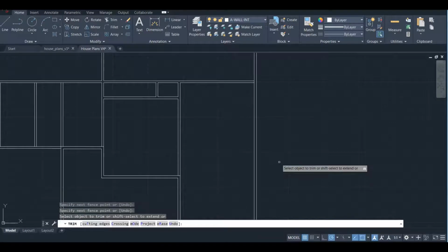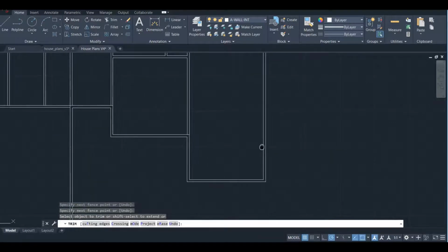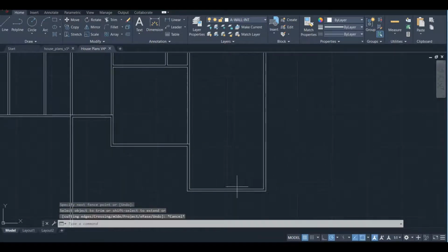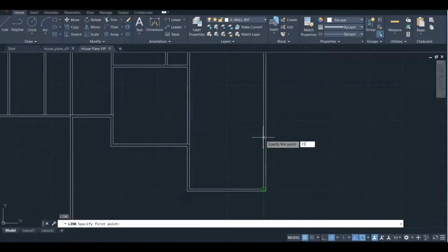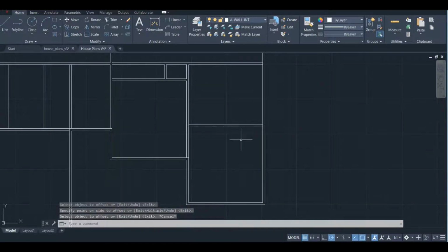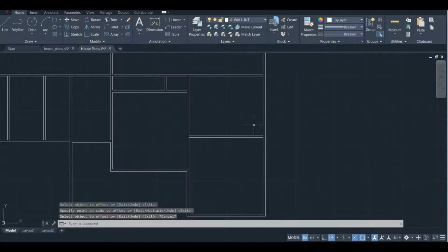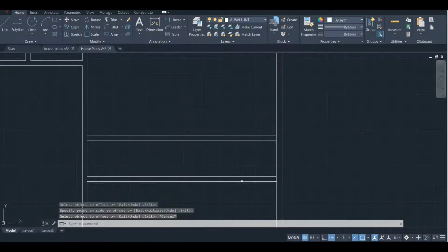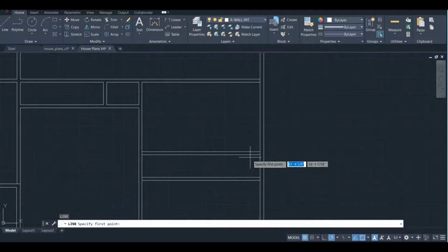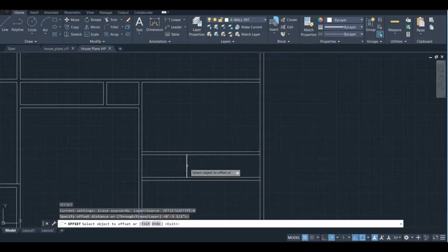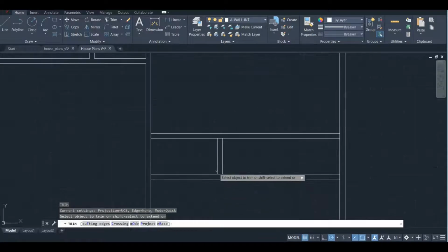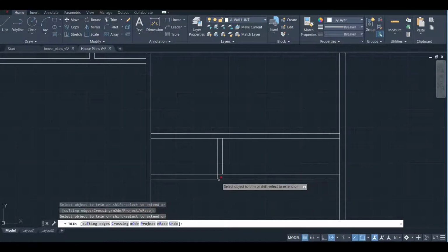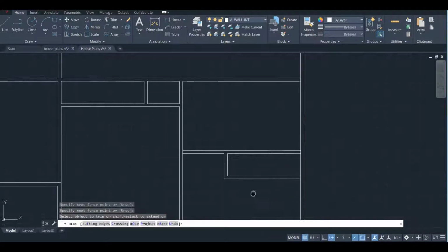This other bedroom is 11 foot 4 inches deep. So draw that wall in. So I go up the wall, and then it's got a closet right here that's 2 foot 1 inch deep. 2 foot 1 inch. The closet is 6 foot 10 inches wide. A cool thing about trim is you can actually hold shift and then it'll do extend instead of trim, because usually you're using trim and extend kind of together.